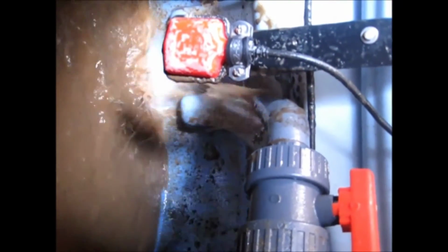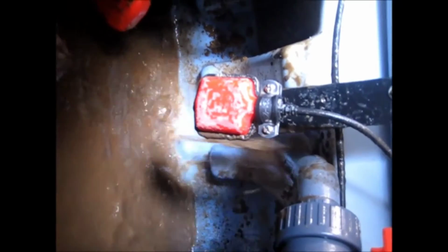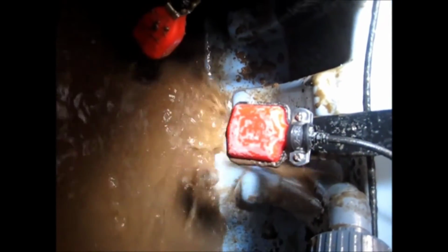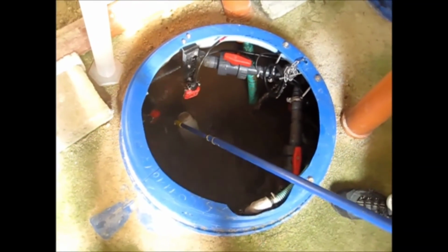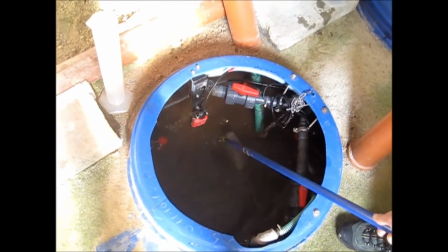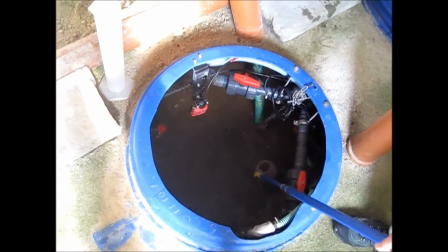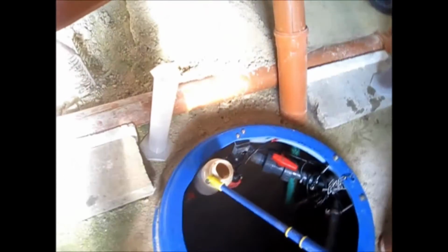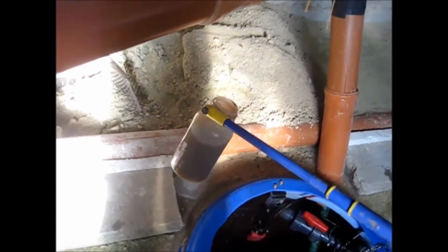Here you can see the wastewater entering the second reactor. Also, this reactor contains microorganisms, which you can see by the brownish color of the wastewater. As a difference to the first reactor, this part is driven with quite high oxygen content. So nitrification and carbon removal take place here.